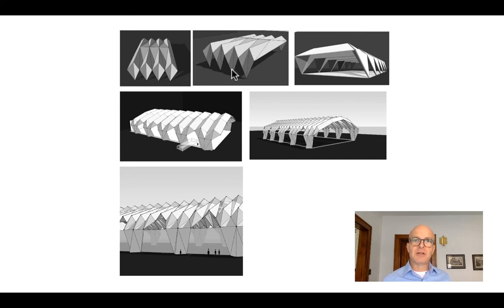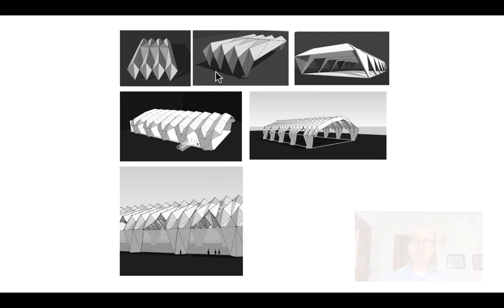And you can see here that those folds allow for some triangular openings on the sides, right? Resolving all of those forces down these compression elements into pin joints at the base, and then opening up spaces in between. So here now we have a folded plate that's responsive not only to the structural consideration, maybe also to the architectural consideration, the long span here, but also to circulation and servicing. Accessible not only from the end, but also because we're using the geometry to open up spaces on the side, we have lots of opportunities for bringing in equipment or vehicles or people all around the perimeter.